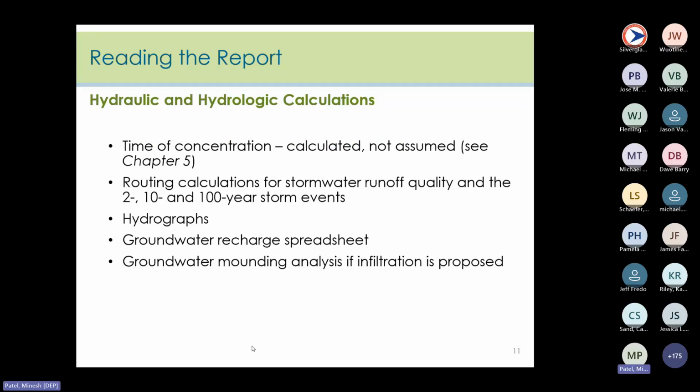The reviewer must be sure that the following calculations are included in the report. Time of concentration, as was discussed in Module 2 last Thursday by Rachel, is essential to characterizing a site. Time of concentration must be calculated and included in the report. Some permittees may even require this information be submitted on a CD so that it can be checked.